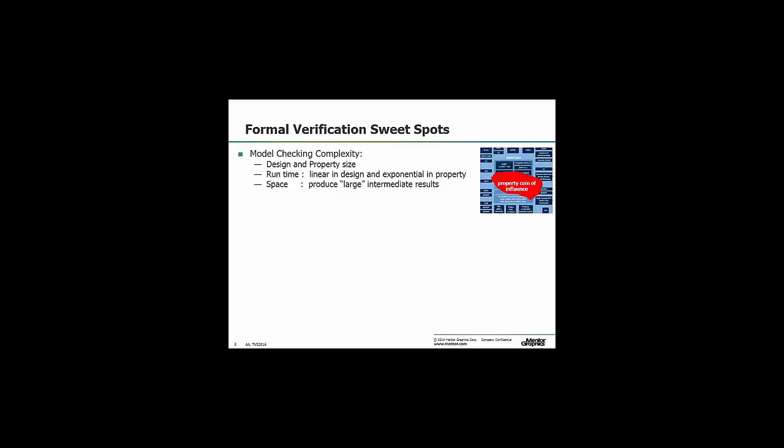To do this, I have to mention very briefly what the complexity of model checking means. As most of you know, model checking is PSPACE-complete. The runtime is linear in the design and exponential in the property size. The model checking algorithms actually work on the FSM that we generated before.